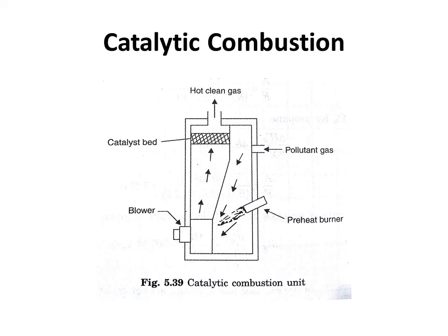Catalytic combustion. This method is usually used when thermal incineration of diluted pollutants is not economically feasible due to additional fuel cost, or when the heat recovery only provides marginal saving. The combustion process takes place in a catalyst, usually at a temperature several degrees below that required for thermal incineration. The different types of catalysts that are usually used are precious metals like platinum and palladium or their alloys. The catalyst is coated on suitable elements like metal ribbon or ceramic rods or alumina pellets.